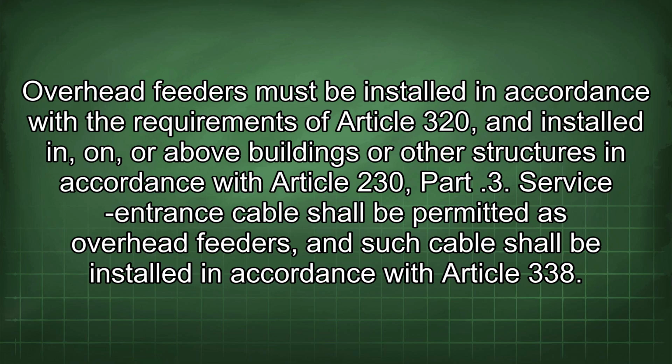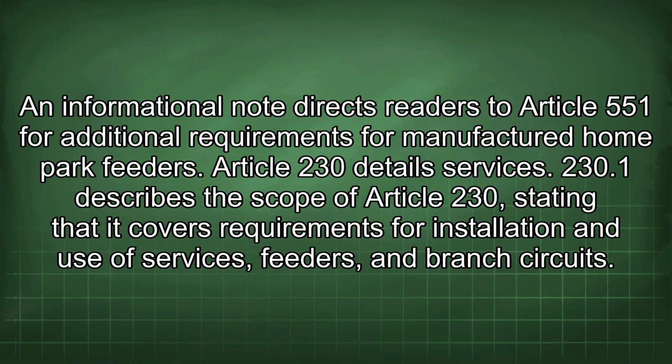Service entrance cables shall be permitted as overhead feeders, and such cables shall be installed in accordance with Article 338. An informational note directs readers to Article 551 for additional requirements for manufactured home park feeders. Article 230 details services.